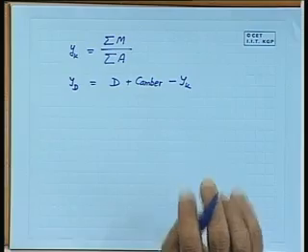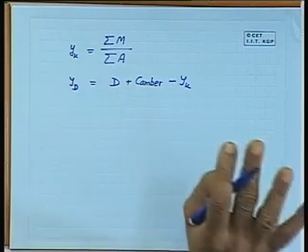The depth of the vessel is measured at deckhead side, from the keel level to the deckhead side, and the stresses will be maximum at the extreme skin on the deck, which happens to be at the crown of the deck, that is at the center line. There you have the maximum camber. So, D plus C, C may be 0 if you are having a flat deck, but usually you have some camber. So, camber can be 0, so I put this equation here. So, I get what is YK, I also get what is YD.